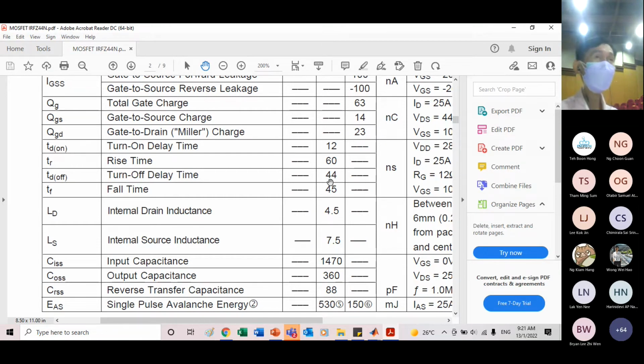Remember field effect transistor? The moment you turn on or off, the field effect and the charge still remain there. It does not disappear immediately. It is still there. Okay, so current still conducts, just like your reverse recovery. So it takes longer time to disperse all the electrons, so that current won't conduct.